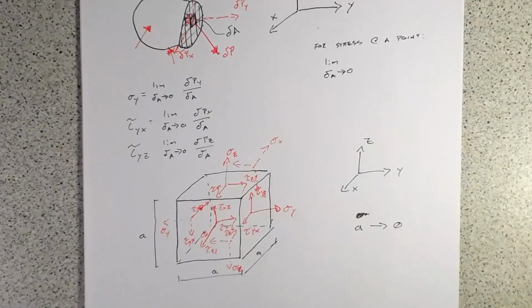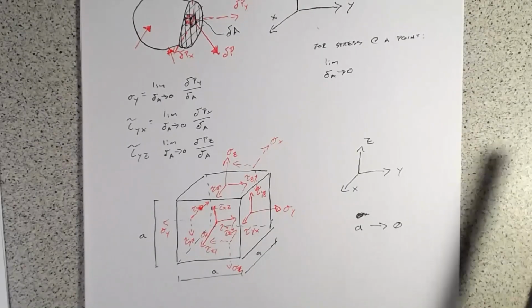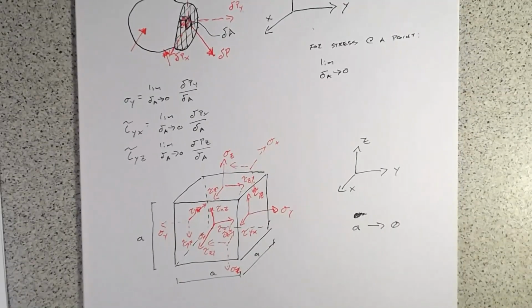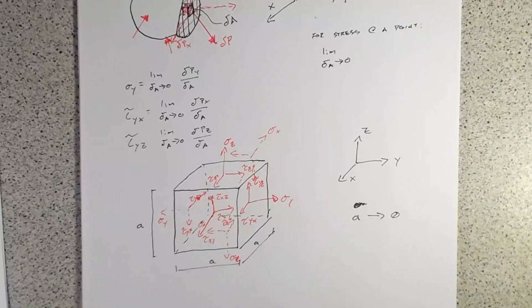So cool. And then you can think of this like when you first started learning free body diagrams. So what we want to do is put down all of the potential forces. In this case, we're looking at stresses instead of forces. But again, the force is just going to be that stress times the area. And then we want to set up our equilibrium equations and see what's the relationship between them? Do we have a force there? Do we not? Is it equal to 0? Is it not? And that's what we're going to work with.